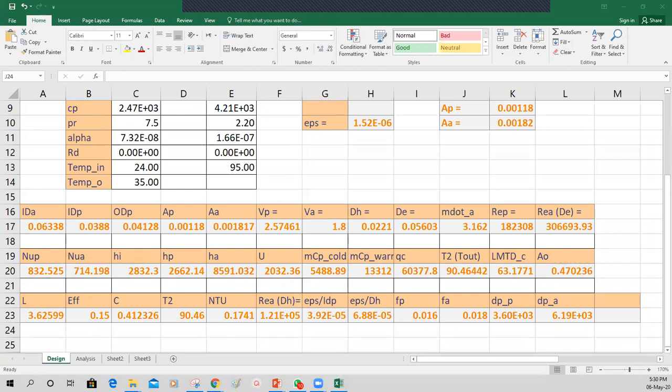Just calculate m c_p delta T and equate it to the power required for the heat. Yes, we need to consider the efficiency. It's a very simple calculation basically. So the tank water heater is simpler than the tankless water heater, right? No. The tankless water heater calculation is simple because this is what I just showed you. The 5 kilowatt, that is the tankless line heater.